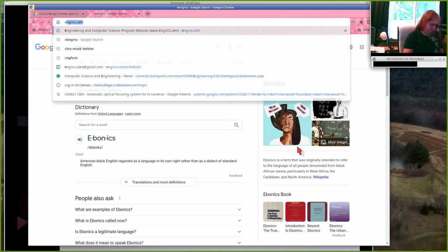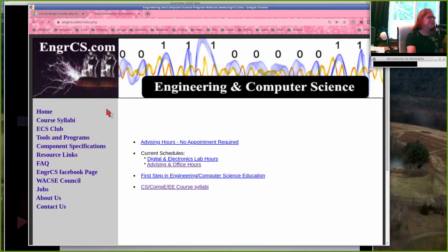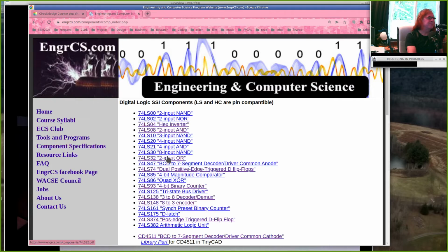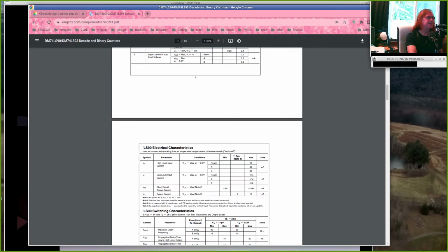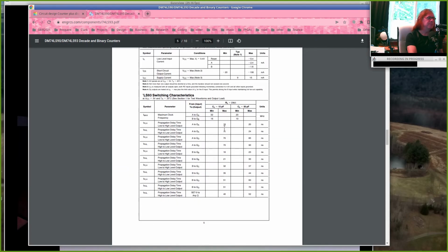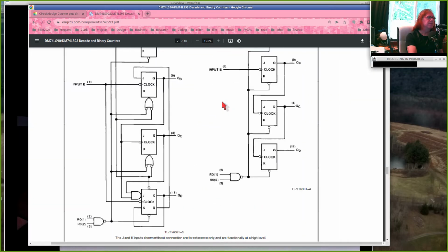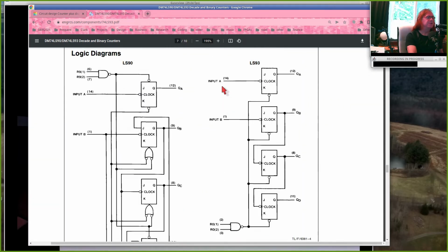And that goes along with the data sheet. If you pull up the component spec on this thing, and you look at this picture of what's going on inside, here's your clock input. It's input A. It's going into the clock of a JK flip-flop, but there's that little circle on the outside. That means it's a negative edge-triggered device.